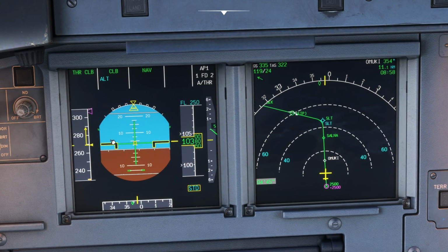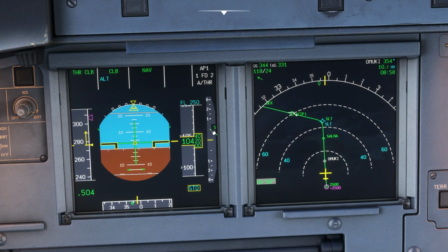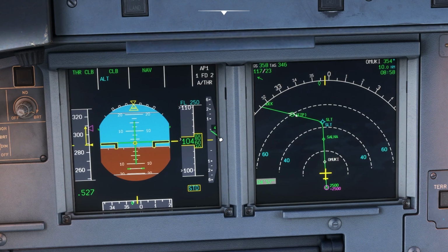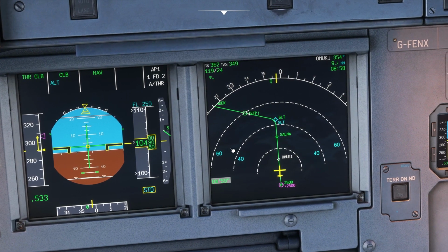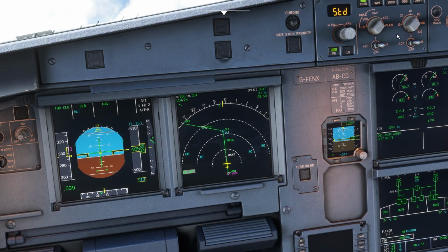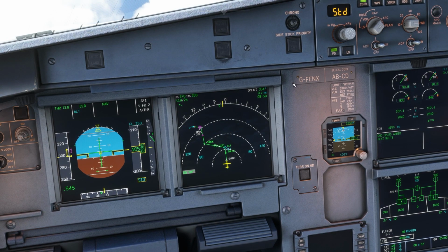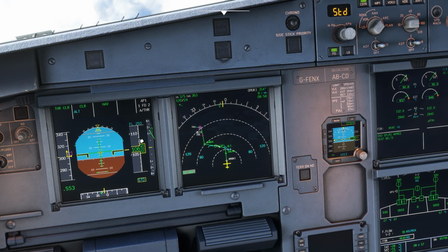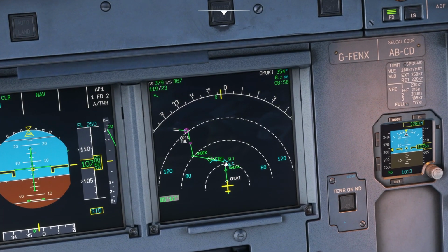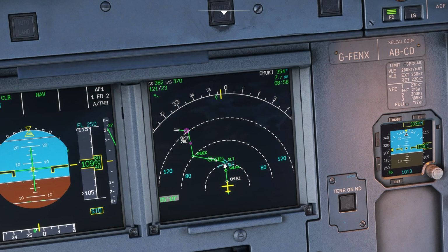Right now you can see the speed is increasing because the plane has crossed 10,000 feet. That's why you can see the vertical speed is reducing. So the moment the speed is roughly 310 knots, I think, then the climb will again start. As you can see now, this top of climb has moved. It is coming over here. So now the vertical speed is again increasing because the plane has now increased the speed. So that's why the top of climb is coming back again. I think, yes, generally it's over here. So till this point the plane is at 25,000 feet.